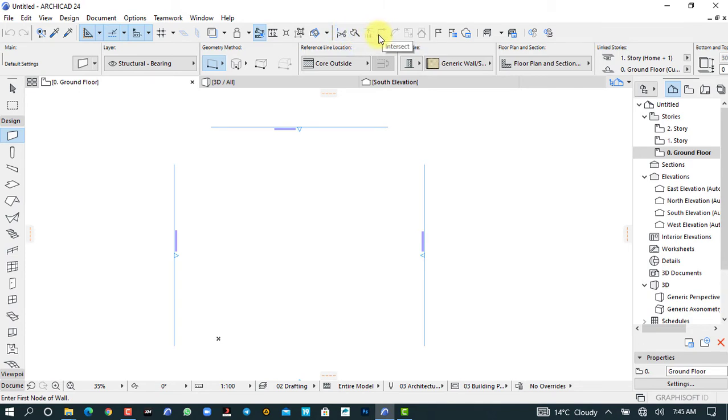And there's the intersect tool. You can draw lines and intersect them. You can add a fillet, chamfer there as well. You can resize, and that's the trim roof. So you can trim walls by roof there. If you have walls which are 6,000 and your roof is at 3,000, you can use that to trim the walls. We will see as we move on using it, and then we will look into those later.